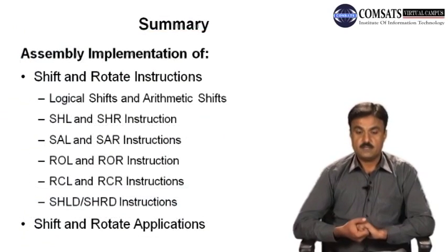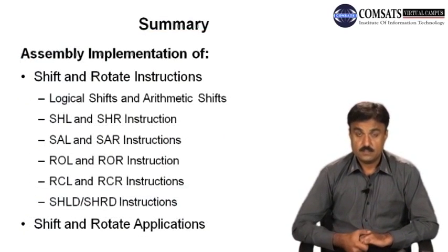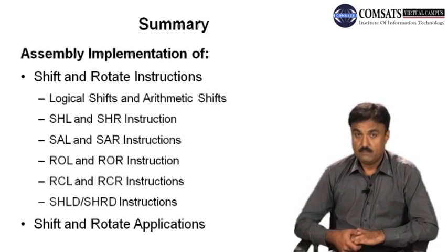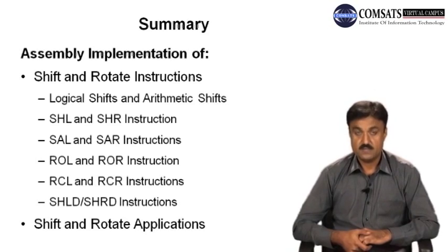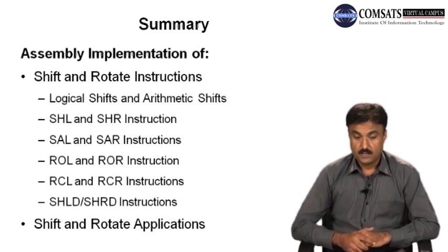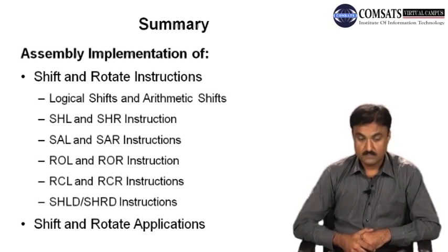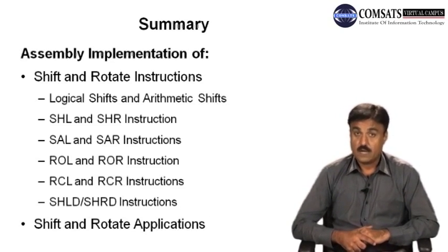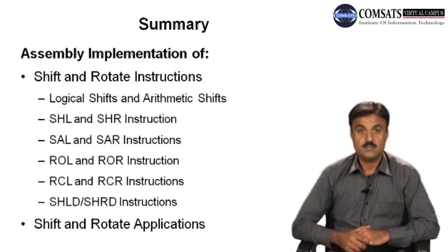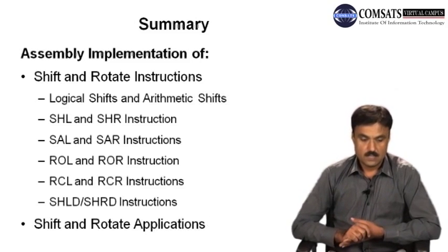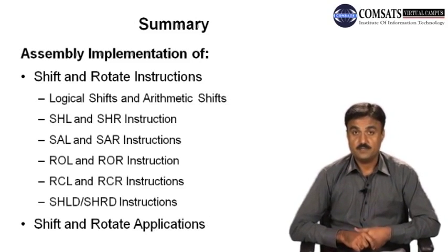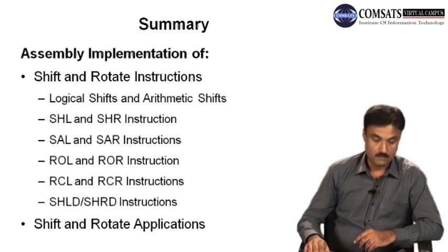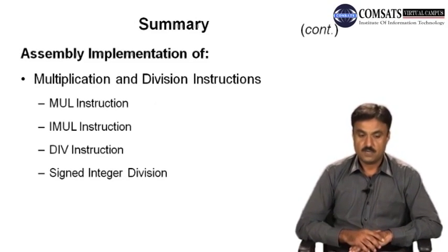Now we are going to summarize. In this lecture number 23, we have implemented the shift and rotate instructions, like logical and arithmetic shift, shift left, shift right, the arithmetic shift left and right, rotate left and rotate right, and the carry also. We also did rotate carry left and rotate carry right, and in this category we did shift left destination and shift right destination. Then we have seen some applications of these shift and rotate.